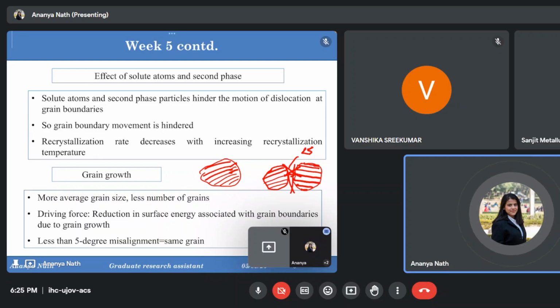That is for dislocations. I am talking about the grains. This is the grain. In the grain, there are the lattices. Inside the lattice, there is the dislocation. I am not talking about dislocations. Dislocations get piled up and they make the new grains. In that case, this 2 to 5 degree, more than 15 degree, these things are considered, because low angle and high angle is something related to the dislocations.